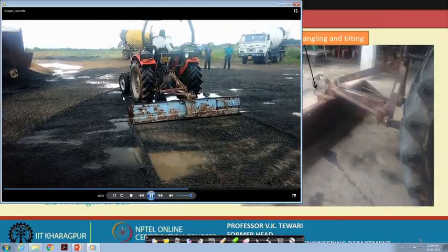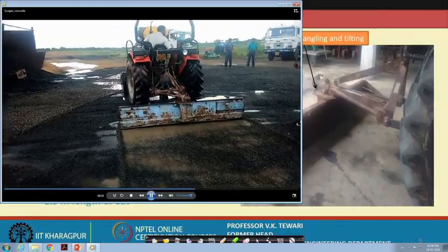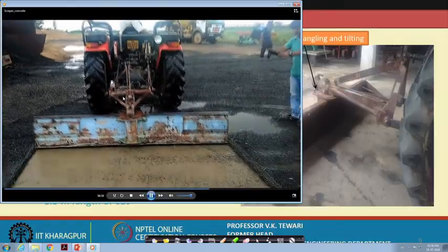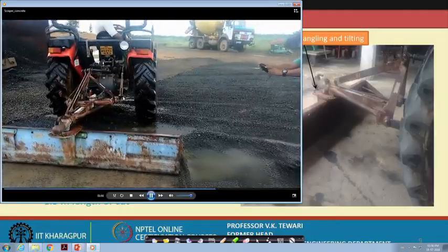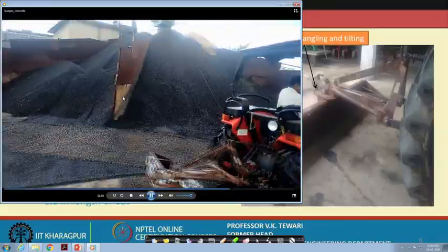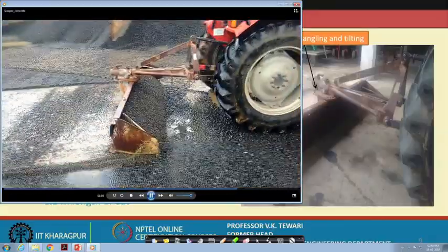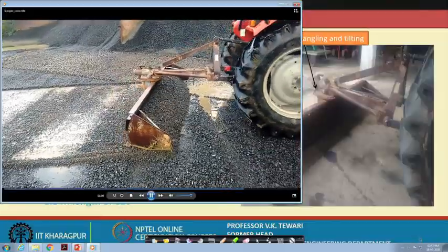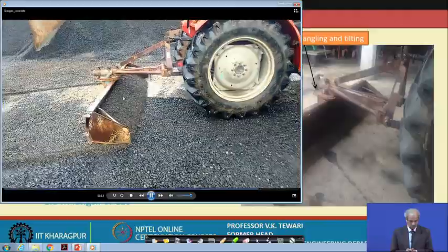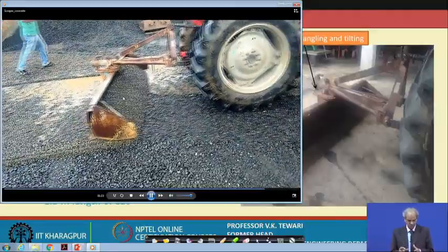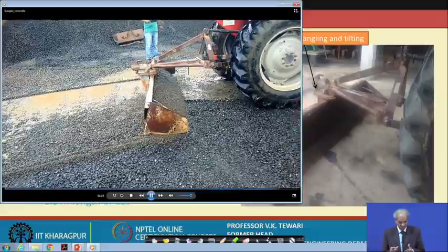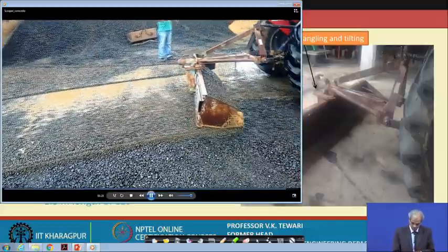One thing one must be very clear about the capacity of the tractor or the size of the tractor when you take these, because these are heavy earth moving machinery. All reclamation machinery, heavy earth moving machinery. You have to be very careful. In fact, you have to take a very high factor of safety when you are working with these machines, particularly the land reclamation machinery, because you do not know what sort of loading will be suddenly coming onto the system. So, this is what it is.